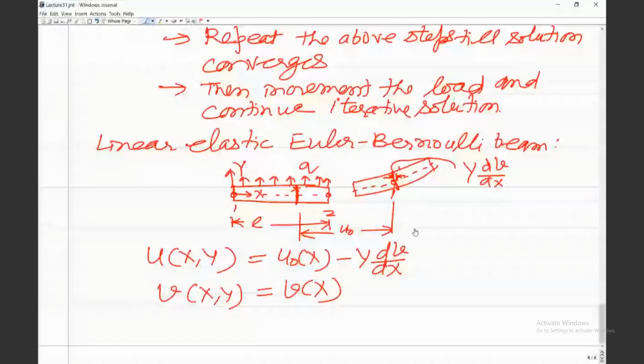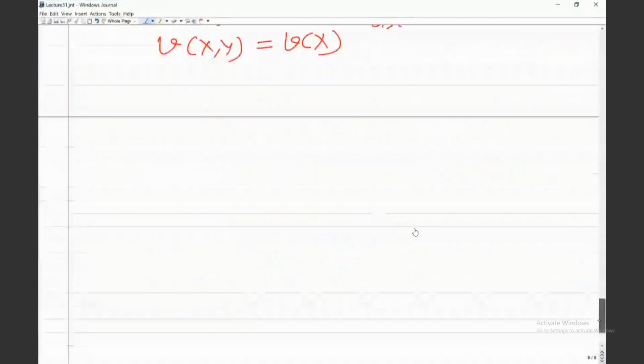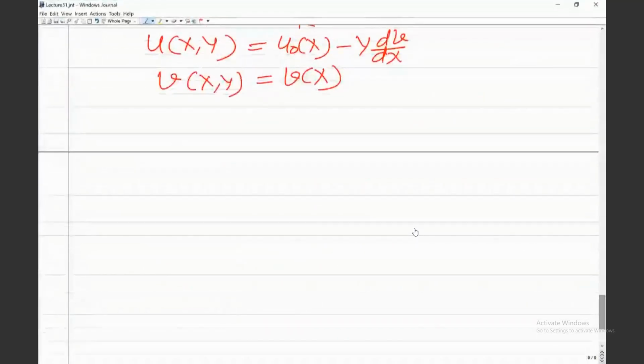Now when we look at the Green-Lagrange strain tensor for this, we write Exx. The only non-zero component of stress here is again Sxx, and the corresponding strain is Exx, because of course because of the Poisson's effect, Eyy and Ezz will also be there, but the independent component of strain is only Exx.